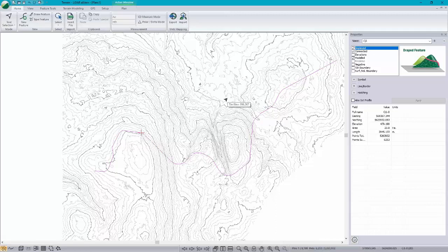We're below the threshold of blowing up the computer because of out of memory. This is often a problem. If you have 25 LiDAR files and they all have 5 million points in them, you're not going to be able to read that data in all at once unless you do the thinning at read time.